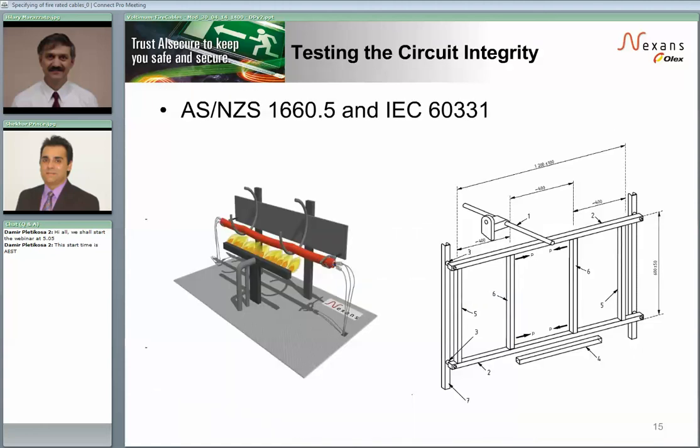In the case of 3013, it's quite different. In order to give the time temperature curve, the test is performed in a furnace. Cables are on a normal tray installed up near the lid of the furnace, and they're installed with two 90-degree bends. On the right here you see the lid of the furnace being removed after a 2-hour test. At that point the temperature of the tray and cables will be about 1000 degrees.